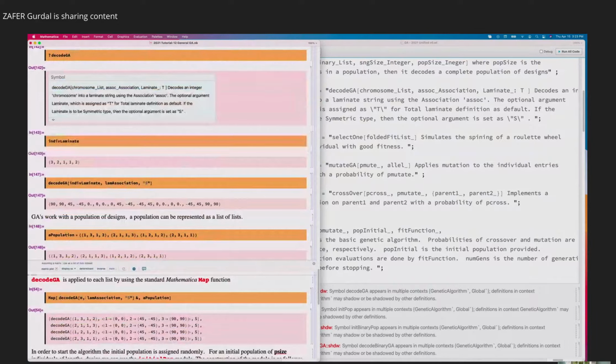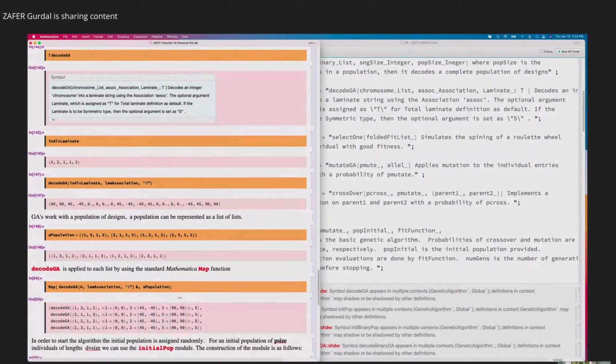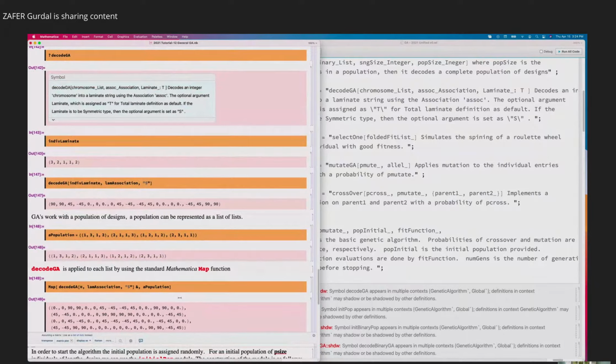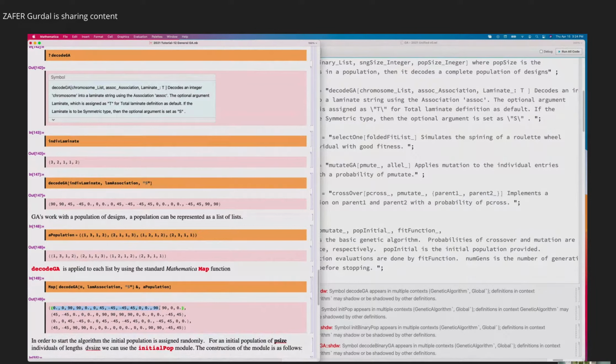Now I can decode that entire thing into my stacking sequence of a symmetric laminate. Now this is, in this case, only 16-ply laminate symmetric, mid-plane symmetric, so it has 16 different orientation angles, being the mid-plane symmetry axis being this.